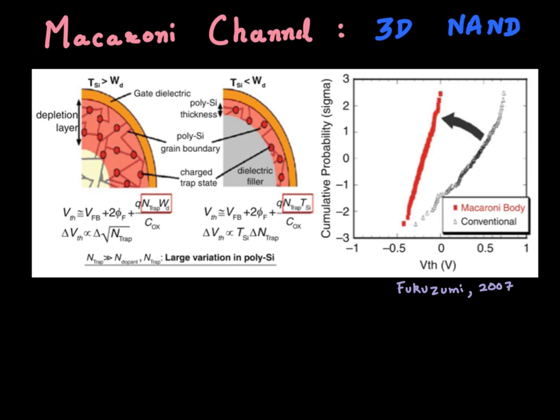So I have again two options here. My option one is to essentially only fill this polysilicon in this small thickness, and fill the rest with a dielectric and oxide. Or I have my option 2, which is to essentially fill the whole plug with polysilicon. So in option 2, what would happen is that this whole plug is filled up with polysilicon, and now